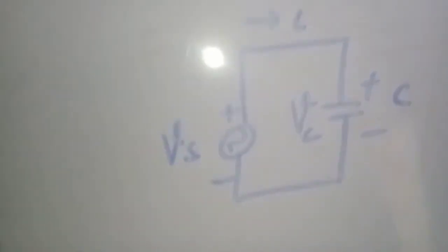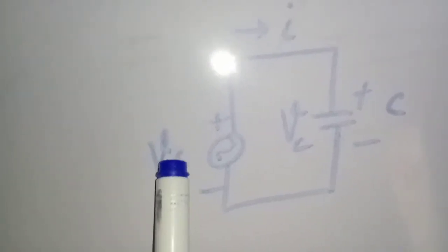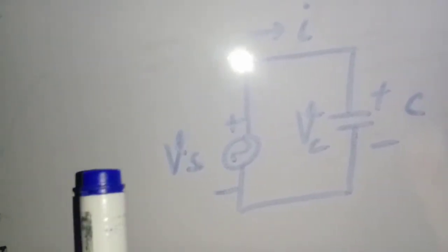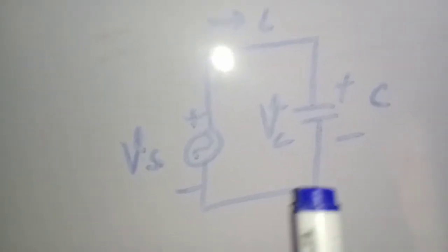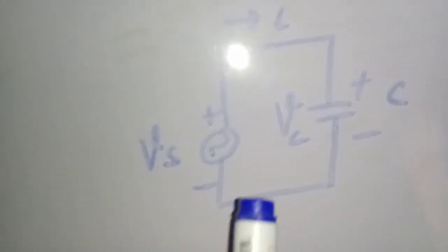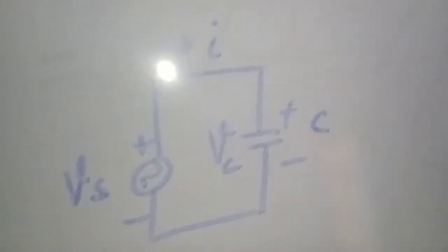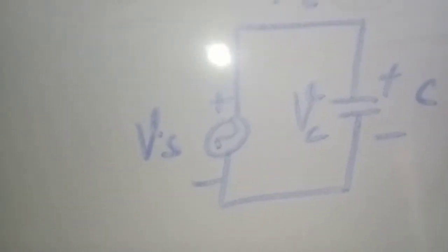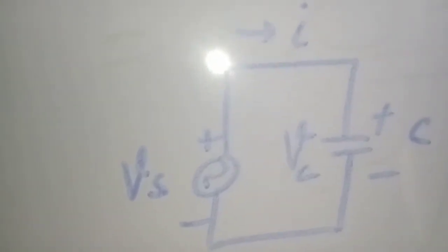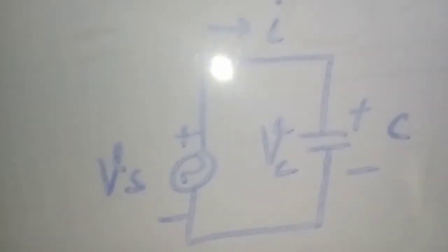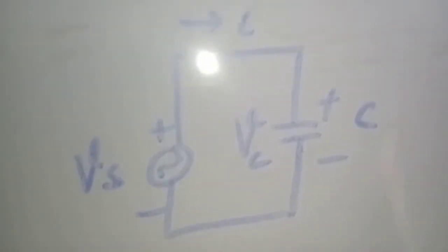We know that when voltage rises here, there is some flow of current in that direction. It means that when we apply a voltage across the capacitor, charge is deposited on the plates of the capacitor as positive and negative. So when the voltage rises, the number of charges increases and more charge is deposited on the plates. So the charge is proportional to the capacitor voltage Vc.